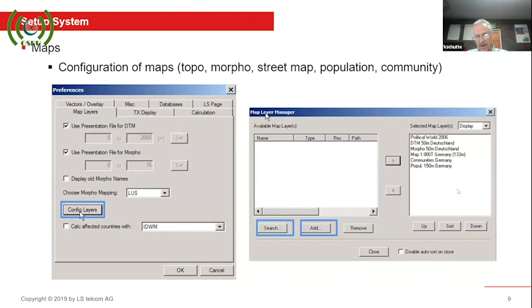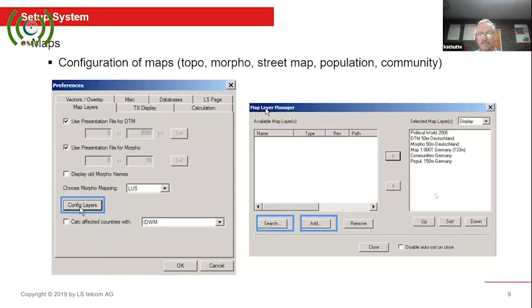So you will typically couple an attenuation factor and a height to your morphology, and that will be used when your propagation model is activated to determine the signal strength or the interference signal at a distance.